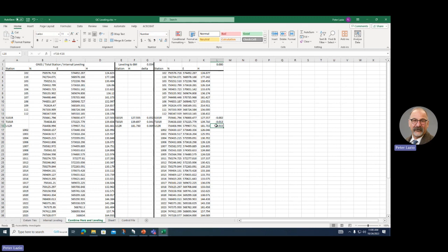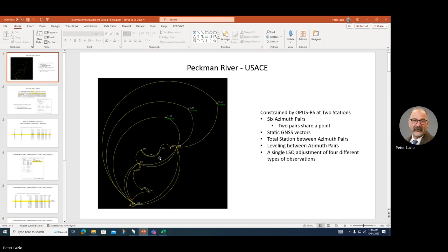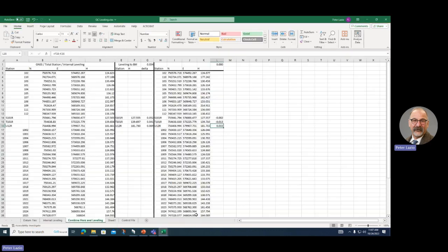So let me do it my way. Right. Now, whether that's going to fly or not, I don't know. But generally, if these were well distributed, one in each quadrant, maybe I might hold them, but generally I just find it easier to move my traverse up and down to fit the benchmark. I'm repeating myself, but on the construction side, if you're trying to localize a site and you hold too much on one side, it'll tilt the plane.